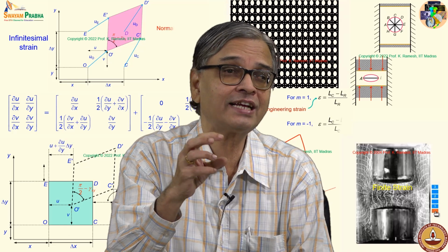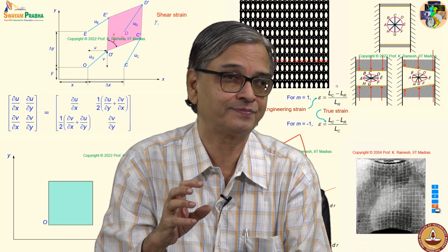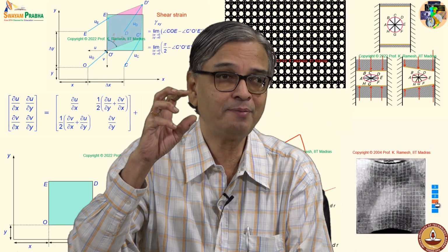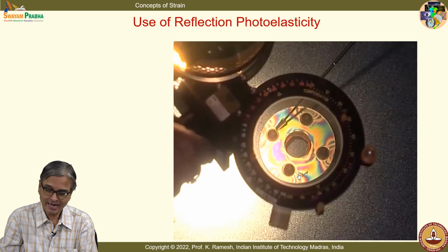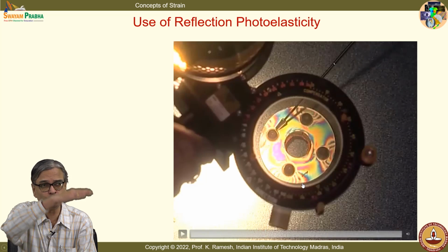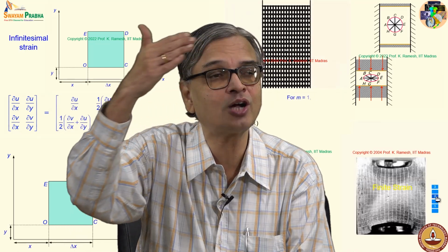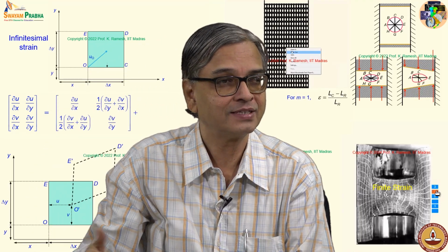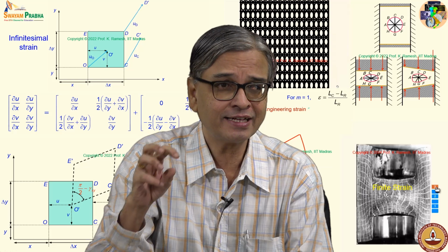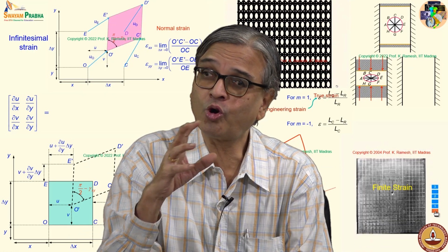In those applications, what people normally do is they use what is known as a torque wrench, and they measure what is the torque to be applied. And when I have a number of bolts like this, here I have only 4, if you have a huge flange, there is a particular sequence in which you have to tighten the bolts. The sequence of tightening influences the performance. You should not do over tightening.